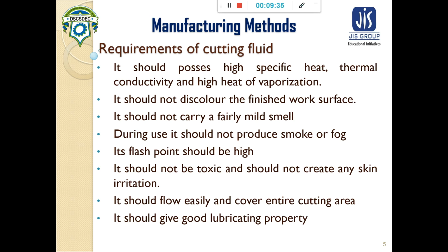So what is needed is that the heat of vaporization of the cutting fluid should be higher, and the application should be selected on the basis of a known value of heat generation. That means for a specific workpiece and cutting tool combination, there is a known value of heat generation, developed over the years by experimentation.